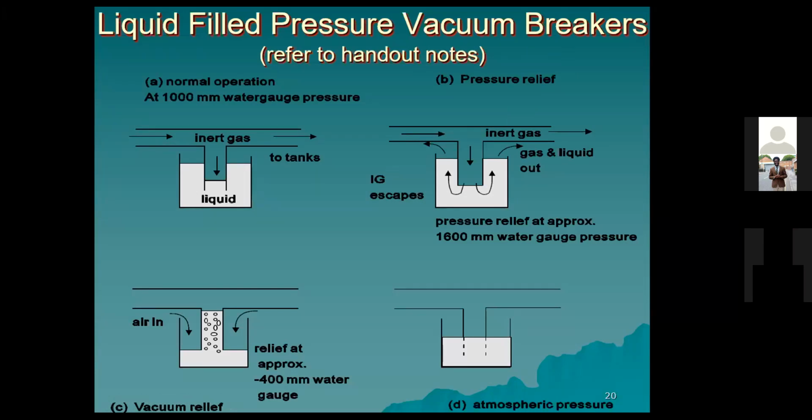You have a form of pressure relief system to release some of the gas that will prevent the tank from over-pressurizing, which can lead to tank explosion. And when the pressure of the tank is very, very low, it can draw vacuum into the tank. So that is the basic function of pressure vacuum relief.